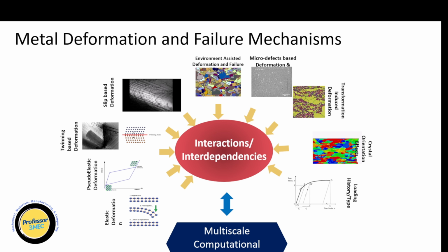I'm going to show you one of the crystal plasticity user material subroutine, which has been adopted from Professor Marine's group. And this was the initial version, which we slightly modified and tailored for HCP crystals. We then later extended it for dual phase materials and also for transformation induced plasticity, as well as for the case if you have material degradation due to environment assisted cracking.